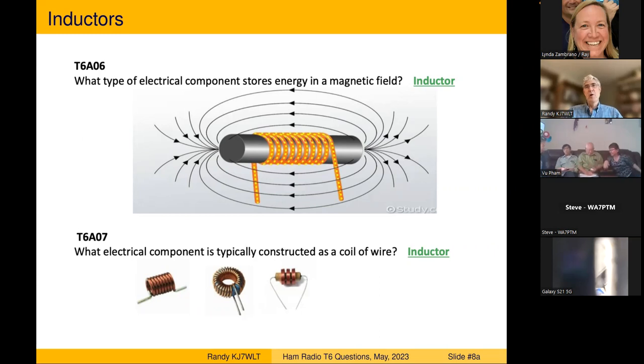And in a current going through a wire, there's an electric current going through the wire as electrons are flowing. But it turns out when a current flows through the wire, it creates a magnetic field in the vicinity of the wire. And if you wrap a bunch of coils of wire around something, then you're basically increasing the magnitude of that magnetic field because the current is going parallel. In one loop of the wire, it's going parallel to the way it's going in each of the other loops. And so if you double the number of loops here, you sort of double the magnetic field that you generate for a given current that's flowing through it.